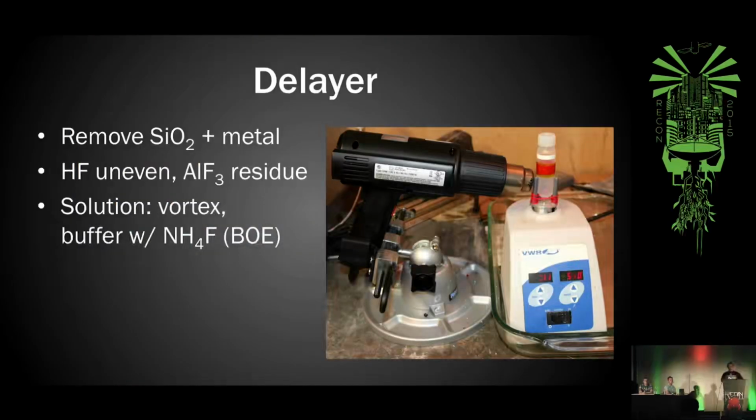Okay, so at this point, we were able to get some top metal images of the chip, the highest layers. But unfortunately for this project, that was not enough. We were looking for the ROM, which we'll talk about a little bit more later, the actual firmware in this device. But we couldn't see it. We could see some metal traces and a little bit below. But we had to go a little bit deeper to get the information that we're looking for.